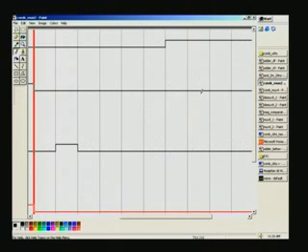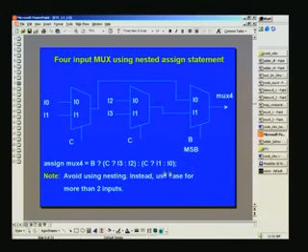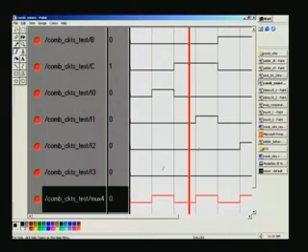Next example was to configure MUX4, that is this. So here I0 through I3 are all the inputs now, and BC are the select pins here, and MUX4 is the final output. B is the MSB here, and we'll see the waveform corresponding to MUX2 and see that all the patterns are intact for this, right?